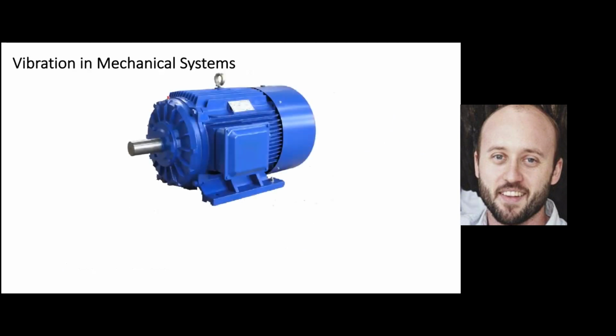Now, going to our practical example that we are concerned with, rotating machinery, mechanical systems in a factory, what we're going to see is the system itself, the vibration starts, we get an excitation from the system rotating. So we have a shaft and say it's rotating at 1800 RPM. It's an excitation to the system. So that is that forcing function that we were talking about.